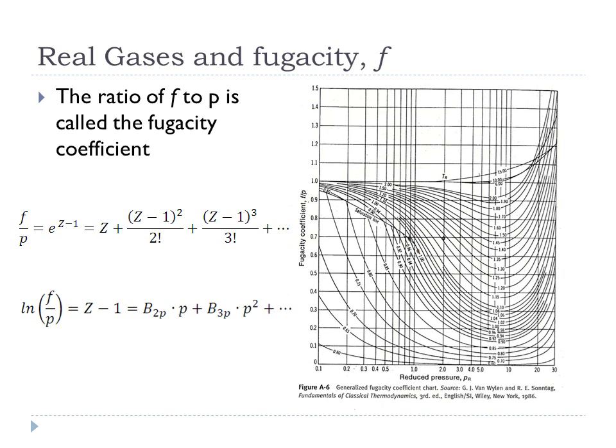And when you're outside of that, it's best to use something like a steam table, where you put in the temperature and pressure, and then you look up what the values are of, let's say, enthalpy, entropy, or anything like that. So that's why in this class, because steam has such a high value of critical temperature, we're going to be using steam tables, Excel-based steam tables. But for other gases like carbon dioxide and methane, we're going to be able to get away with a first order van der Waals approximation.